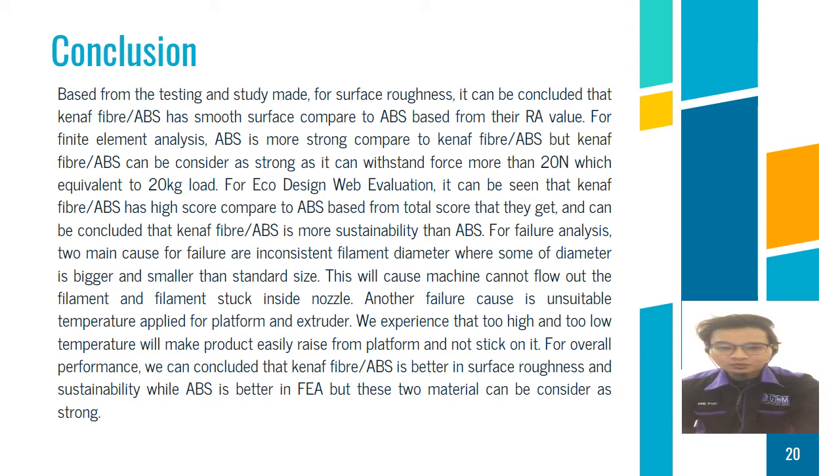Then for the eco web design evaluation, we can see that kenaf fiber ABS is more sustainable compared to ABS, based on the total score that we get. And lastly, for the failure analysis, we consider two major causes of our failure during printing: inconsistent filament size and unsuitable parameters. If we can overcome these two aspects, then we can print our product successfully.